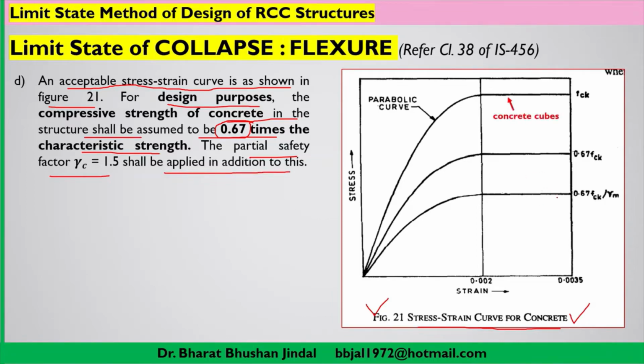So now you will be able to understand. See here, the very first curve is giving you the graph for the characteristic compressive strength of concrete. This graph is basically the result of testing of concrete cubes. When you test the concrete cubes in the laboratory, you may get this type of graph between stress and strain. Now the second graph is basically for when you start using concrete in the structure.